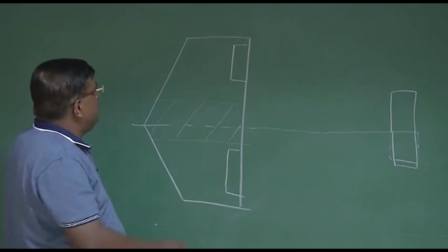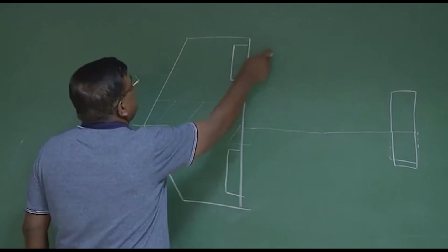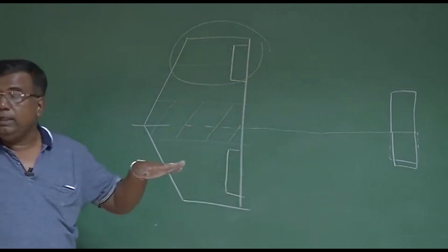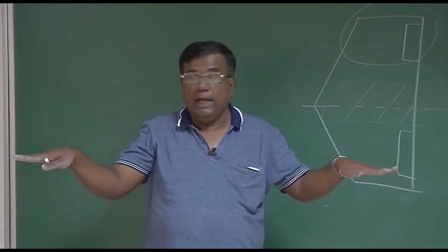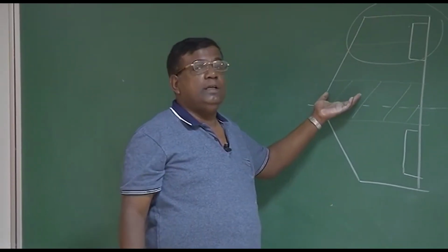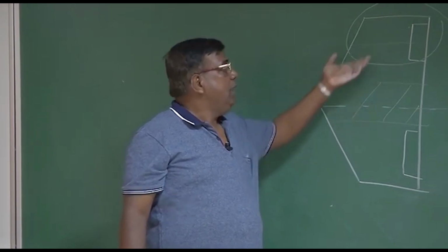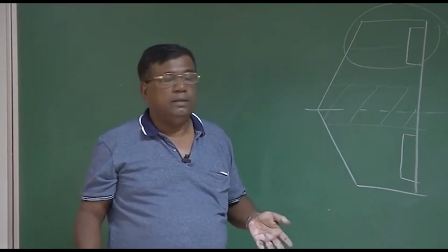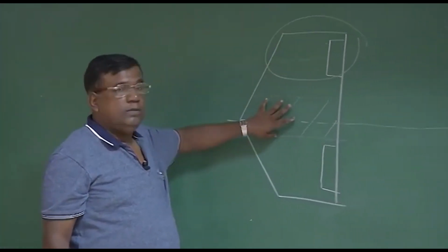So one way is we give a geometric twist. At the tip, you put a slight negative angle, so that even if here it is around 12-13 degrees, which is closer to a stall, the area here is seeing less, about 2 degrees less than 12 or 13, so that this will not stall, but the root will stall.